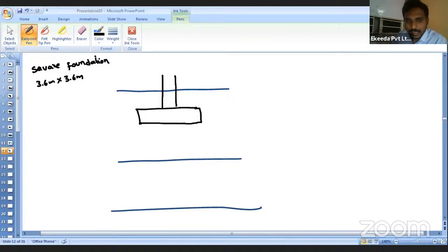So as the load is applied on the foundation, how will it behave? Obviously, because of the construction, the load will be distributed through the soil. It will not always be distributed uniformly. So if we don't know how the stress is distributed, then we have to imagine it like a trapezoidal stress variation. That means imagine that the stress variation is acting like this.